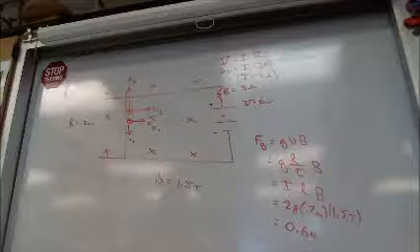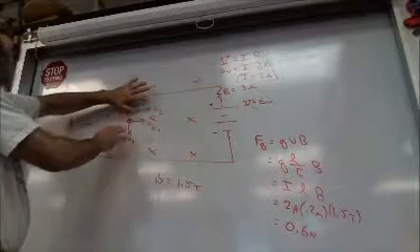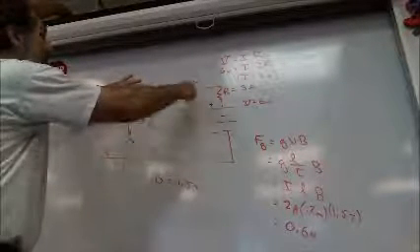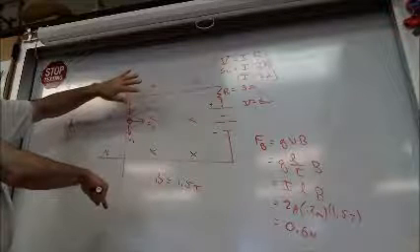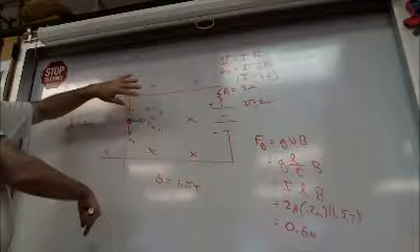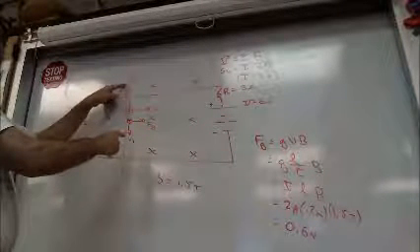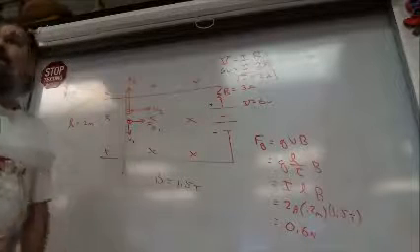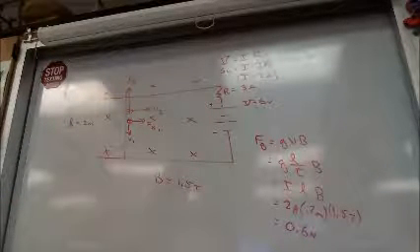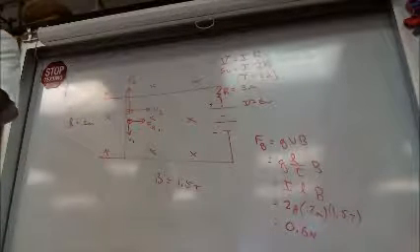Can you say that again? What I'm saying is, before the wire started to move, we could say that there was a current going this way, right? That current came from the battery, making this go down. But now, as this wire starts to move, this magnetic force is generated, and that's opposing what the battery's trying to make the current do. Okay, that makes sense. So will the current increase or decrease? It's going to have to decrease now, won't it?